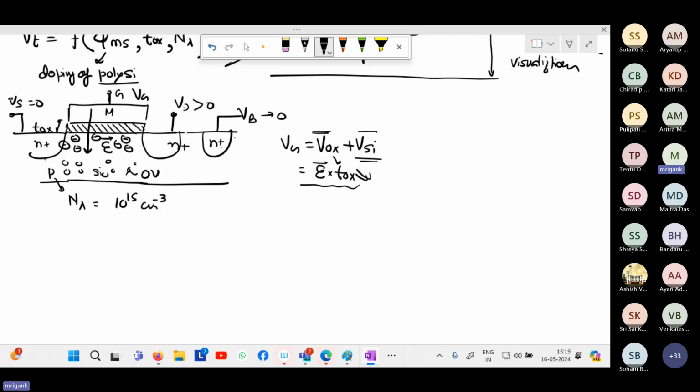And then there is a continuous channel formed between source and drain, and the current can flow between source and drain. If you remove that positive potential, then that channel is gone, and in between the source and drain, you have a p-type substrate, which is not going to allow the current to flow. Is that clear, all of you?